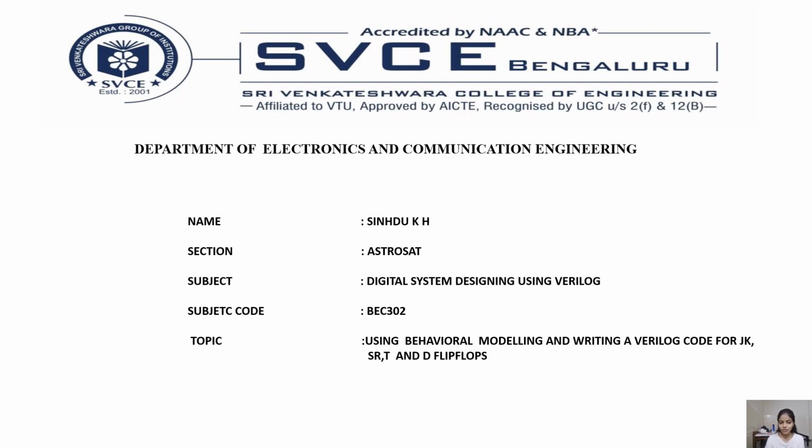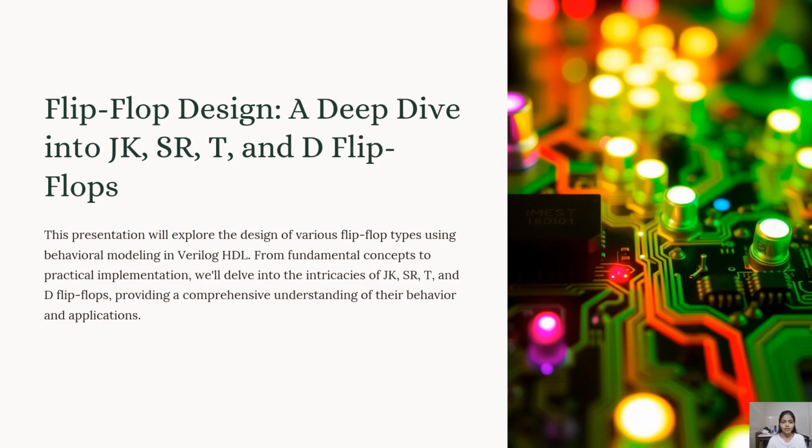Today we'll start this video with a topic using behavior modeling and writing the Verilog code for JK flip-flops and different types of flip-flops. A deep dive into JK, SR, T and D flip-flops.